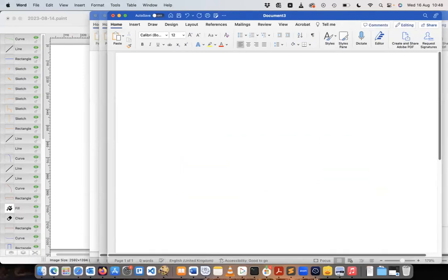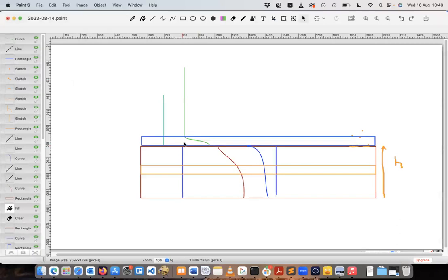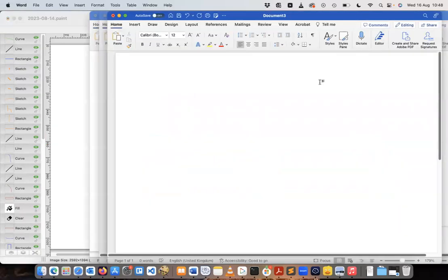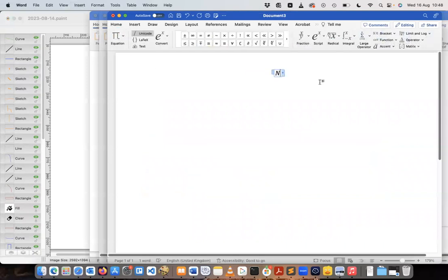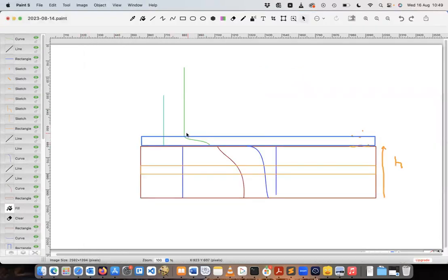Okay, so we would like to write this expression for the film here. We would like to understand the molar flux in the air that's sitting above the slab. And so we said last time that the flux of our water in the air, according to film theory, could be represented more simply as Kc times the concentration difference. If we look at the concentration difference, we can see two concentrations here.